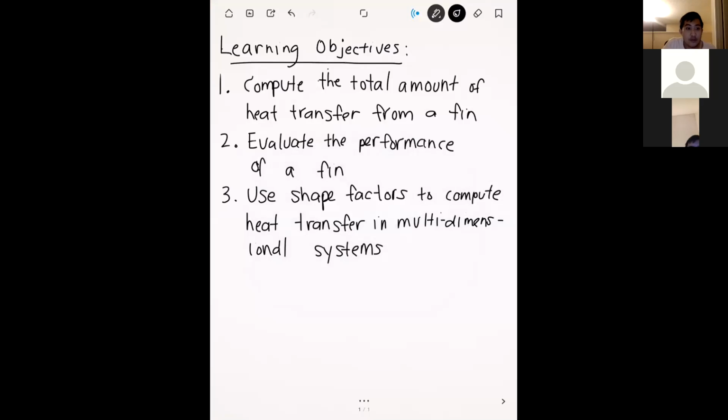Actually, I had a quick question on the homework, if you have a second. Sure, what's up? On the problem with the eyeball, when you're doing the thermal circuit without the contact lens, I'm confused about which radius to use for R outer. Would you just use the same radius two to calculate the surface area? Right. In that case, since you don't have the contact lens, the outside air is in direct contact with your cornea, so the R that you would use in the convection resistance would be R2. Okay, that's what I thought.